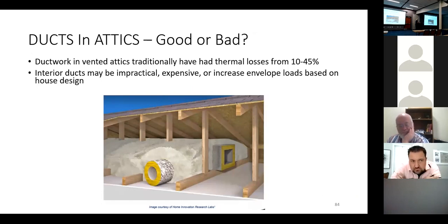The problem is not just the conduction we talked about, but what happens if the duct leaks? So our supply air leaks. Let's say it leaks 200 CFM anytime that unit's running. So we're throwing away 200 CFM that we just spent money to heat or cool. Well, that doesn't make very much sense. But what does it do to the house? If we leak 200 CFM out due to a leaky supply air duct system, it has to be replaced with 200 CFM that leaks in.